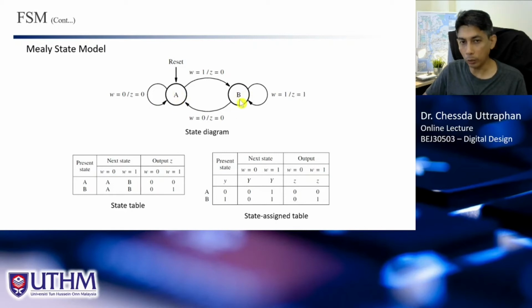If we have more than two states, you cannot use 1 bit, because 1 bit can only represent up to two possible numbers. If you have 3 or 4, you need to have 2 bits, because with 2 bits you can represent up to four states, and 1 bit means 1 flip-flop. All right, 2 bits means 2 flip-flops, 3 bits means 3 flip-flops.